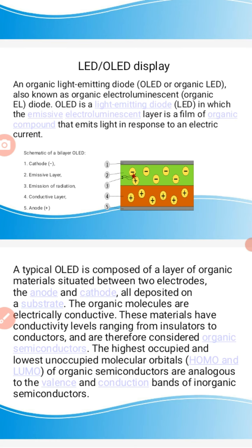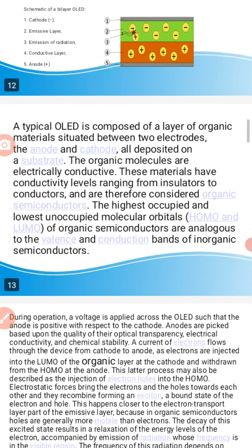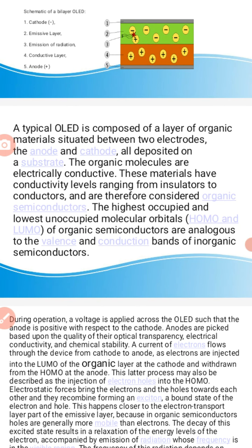An LED consists of two slabs of semiconductor materials, one of which is slightly rich in electrons, or slightly more negatively charged, while the other is rich in holes, that is p-type material. When we join these two slabs together, we get an electrically neutral area at their junction, where excess electrons and holes jump over to the other side and cancel each other out.